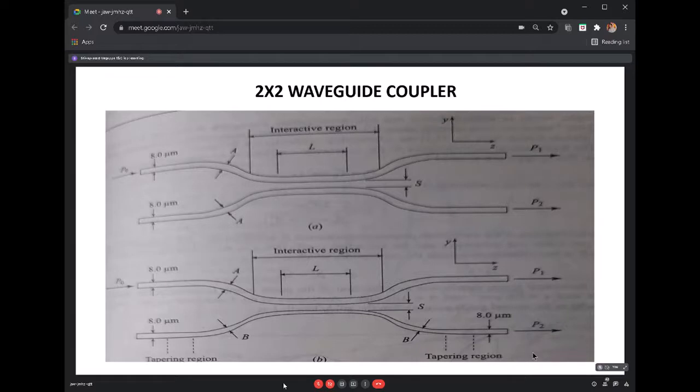When I discuss the Mach Zehnder interferometer, I'll show how it can be expressed as a 4 terminal device. That means it will have 2 inputs and 2 outputs, as you all know, right? Here you can see 2 inputs as well as 2 outputs. So it can be expressed in the form of the scattering matrix, that is B is equal to S into A. The scattering matrix, which we call S here.